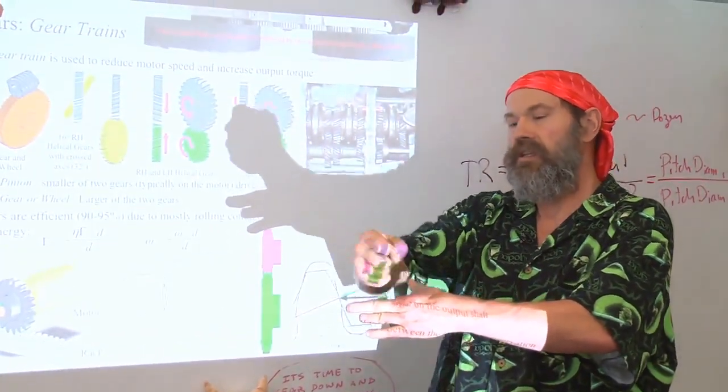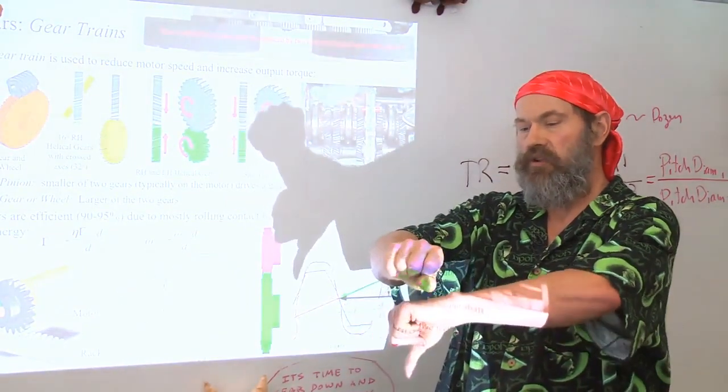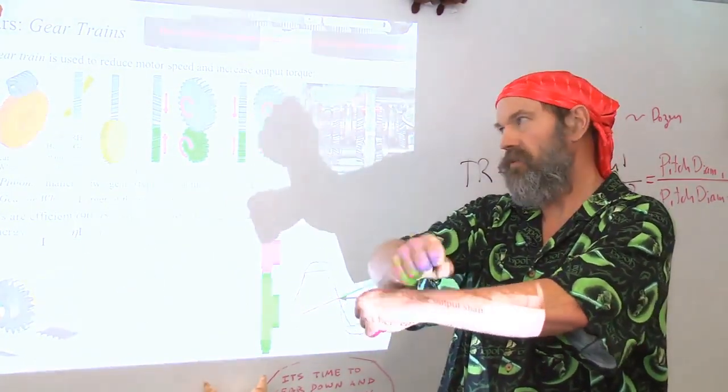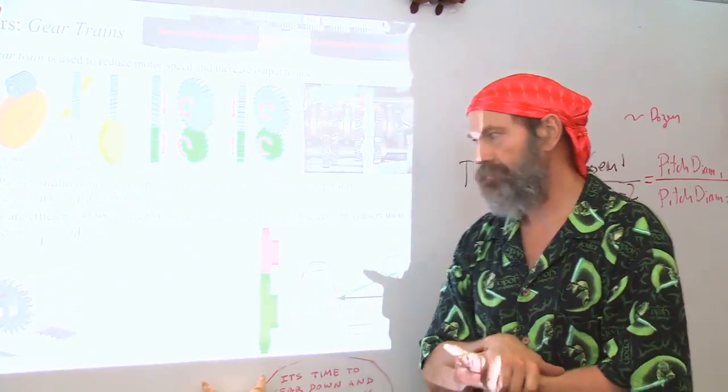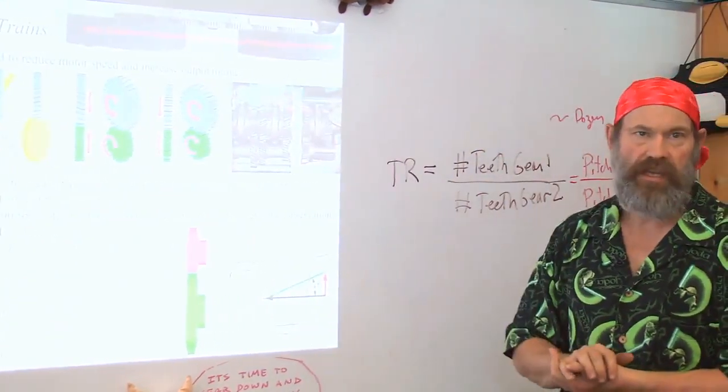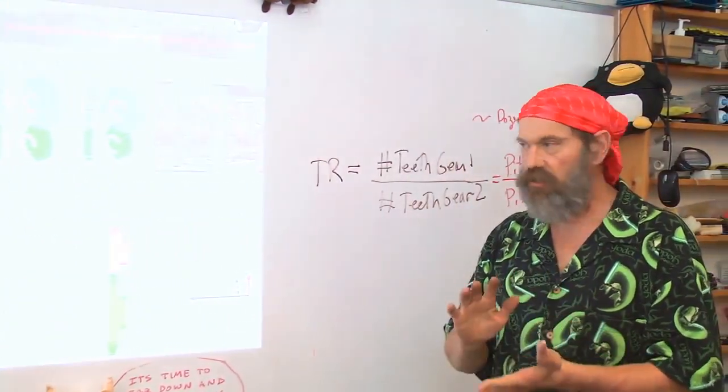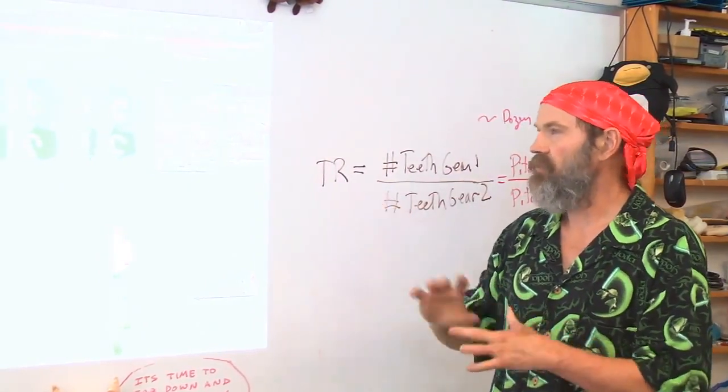So one shaft is moving this way and you want to make it turn a right angle. Helical gears can do that for you too. Worm gears can give you very high ratios. Fantastic opportunities you can do with gears.